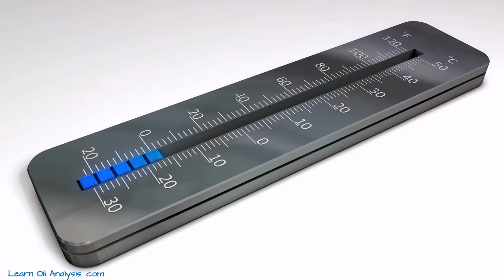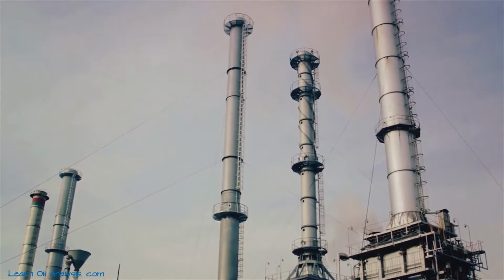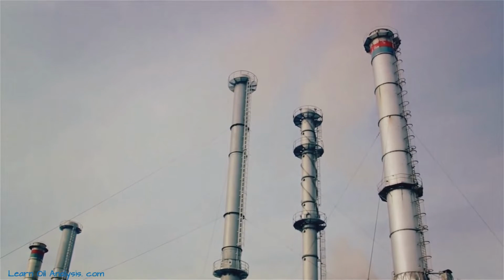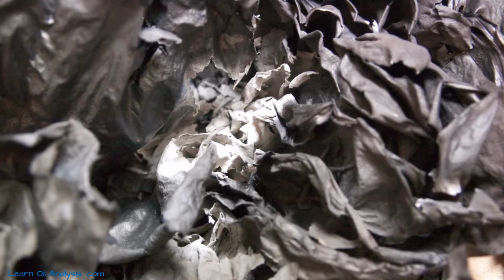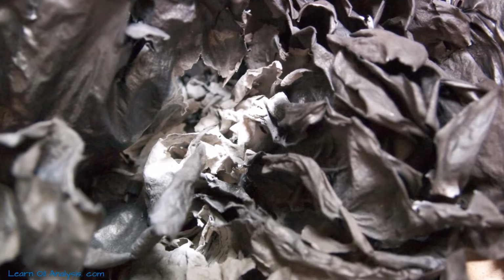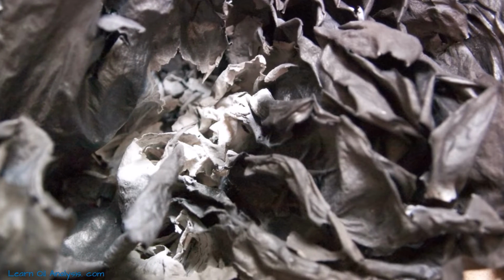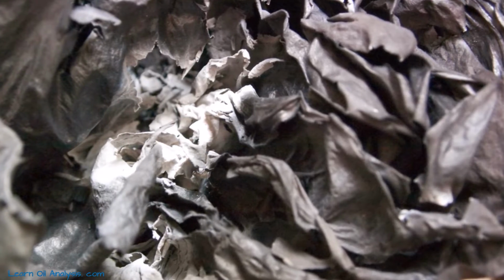High temperature overheating, as the name suggests, results from excessive heat. The high temperatures cause the thermal cracking of the oil, producing ethylene, similar to how a refinery manufactures synthetic lubricants, but in reverse. So think of high temperature overheating as winding back the clock and chemically changing a molecule into some of its constituent parts. When paper insulation breakdown occurs, the cellulose in the paper undergoes pyrolysis, resulting in the release of carbon monoxide as well as furans, although let's leave furans for another video.